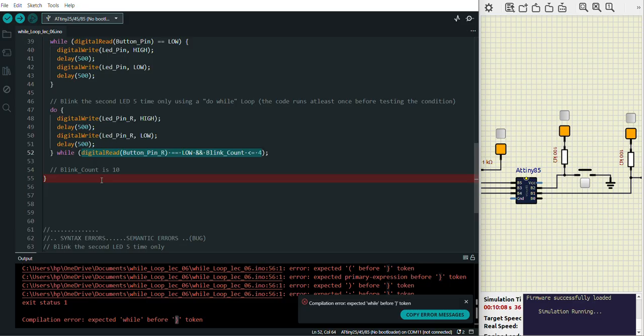Let me give you a quick example. A few years back, I was working on a project, something to do with solar. I was designing a high-powered DC circuit breaker. We had to first connect the load, measure the voltage and current, then detect whether it is an overload, then maintain the connection or disconnect. But we had to first connect.